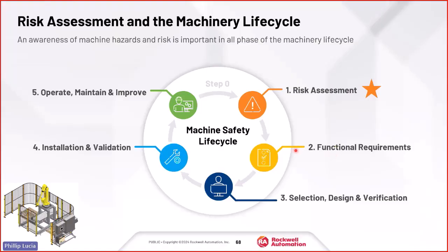Functional requirements documentation is a kind of pre-engineering statement that says how those functions should be designed. Then we get into the real engineering: selecting devices, making schematics, programming, etc. And then we verify that design, using some math tools I'll touch on later, to check whether our design satisfied the risk assessment and requirements documentation. So verification is an extra step, again not particularly hard or complicated, and something we can help with. And then ultimately we install it and validate that system.